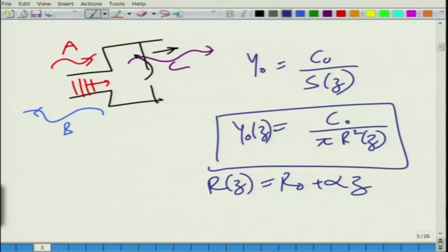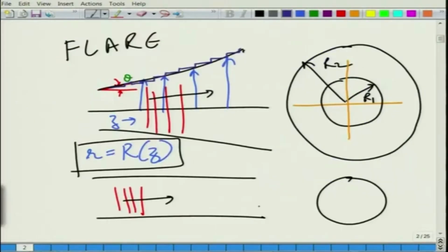So, how is it affecting the wave propagation? How is the governing equation changing with the addition of such things? And we saw that the transmission loss of a simple, uniform tube was 0, because across points 1 and 2 there was no area change; whatever wave is propagating in this direction, there are no reflections, there are no area changes to reflect it back.